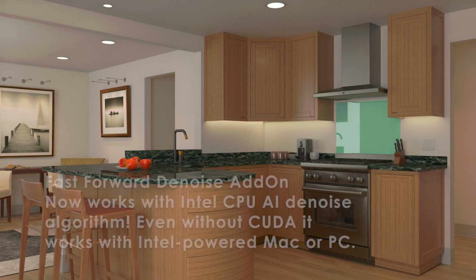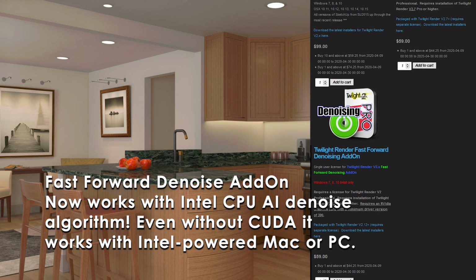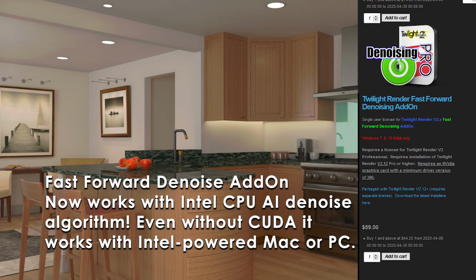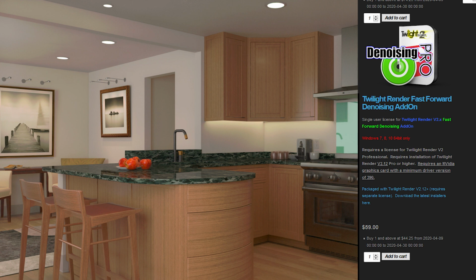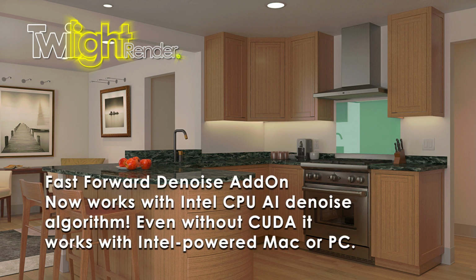But I highly suggest, if you have an NVIDIA graphics card, to get the Fast Forward plugin for Twilight. The Fast Forward plugin will denoise your image. So all of these images that you're seeing were rendered with Easy 09 render setting for final rendering. And they do take a while to clear up the noise. When you use the denoise Fast Forward plugin with your NVIDIA CUDA graphics card, it really cuts the render times down and gives you great results.